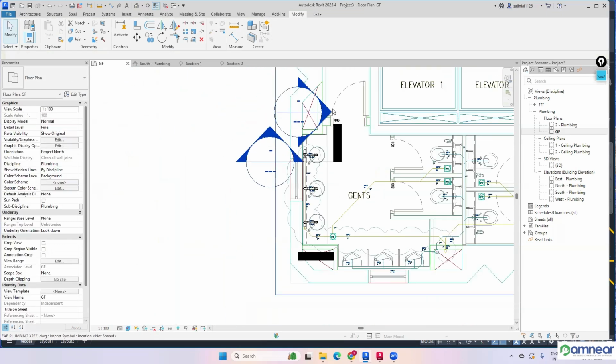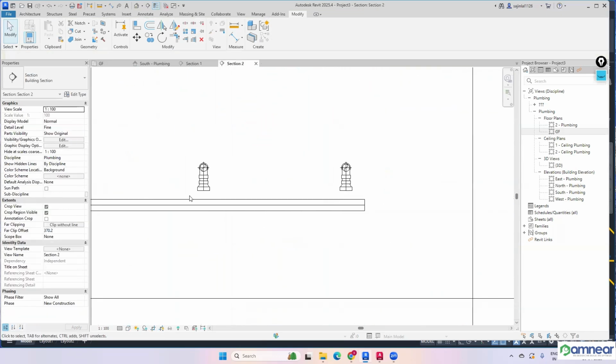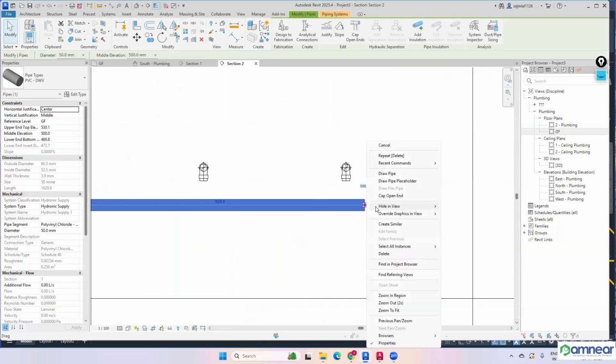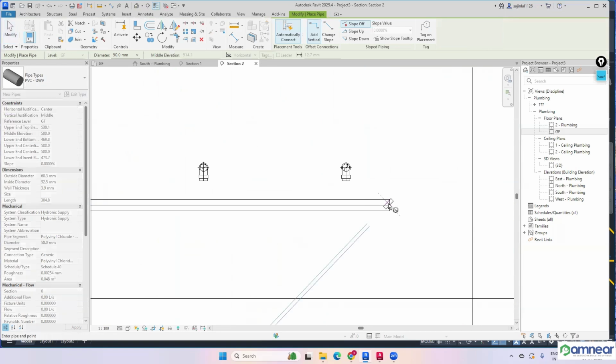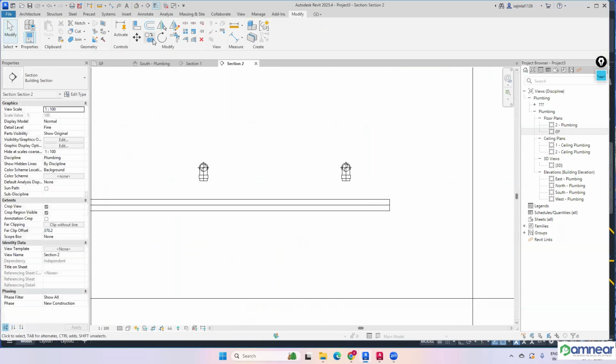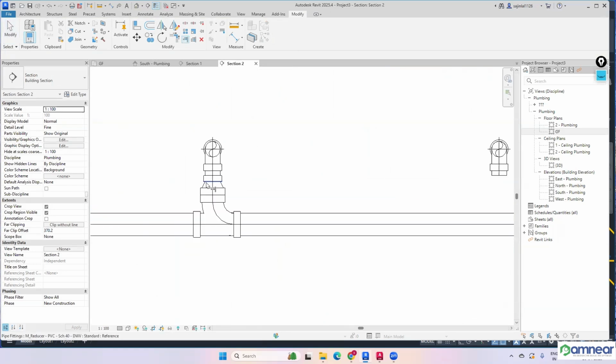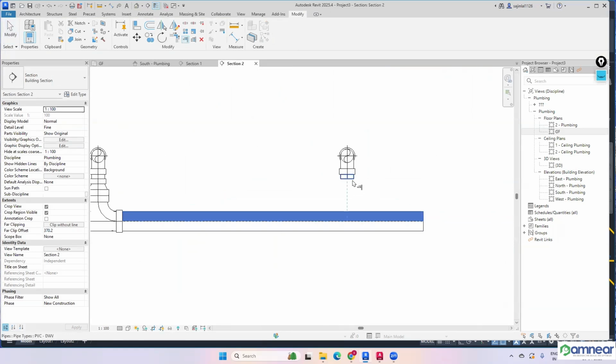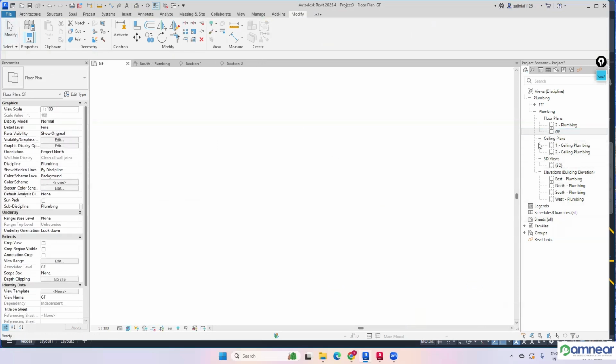Now we can connect that as well. Since we have copied, I don't want this one. Trim and Extend. So this pipe we can move slightly. We can adjust that. Okay. Trim and Extend Single Element. Select this one. Connect it there. Select this one. Connect it there. Okay. Now just split this pipe. Delete. Go to the ground level.